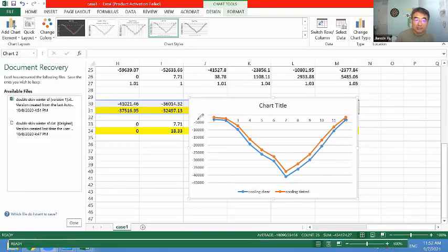Now in DesignBuilder, to represent cooling, it uses negative signs, right? So all of these numbers have negative signs. It just means that you're removing heat from a space. But in terms of the level of loads, you're still looking at the absolute value. So 45,000, that's almost like 4 tons of cooling. Just ignore the minus sign. The minus sign only represents cooling. That's here, in July. You are in that neighborhood. That means you have to have that much cooling to maintain the comfort temperature.